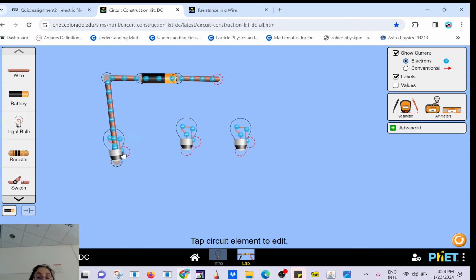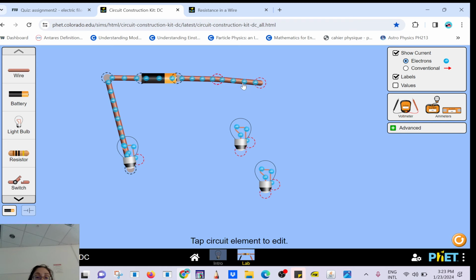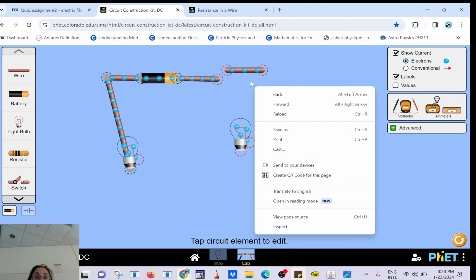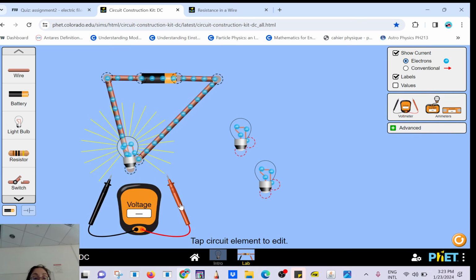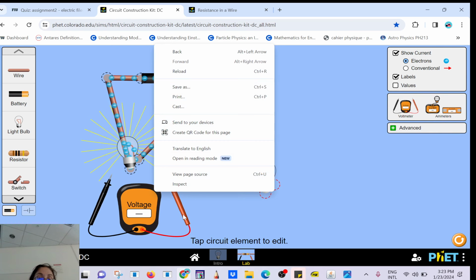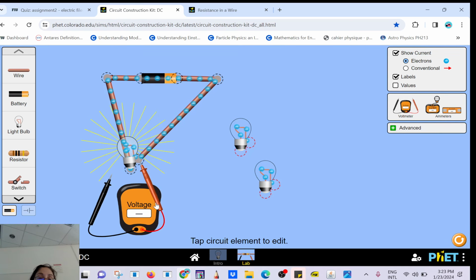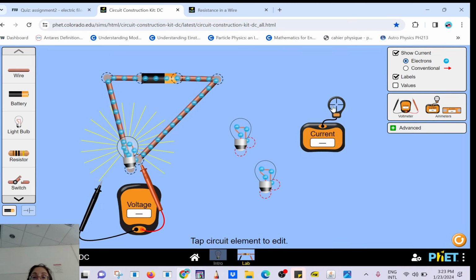3, right? So here you have only one. If I take only one here, if I connect, is it happy? Yeah, it's happy. Let's check. Does it get the 9 volt here? It was promised. Yes. Okay. And the current here, I can measure the current. It's gonna be 0.9, right? So 9 divided by 10.